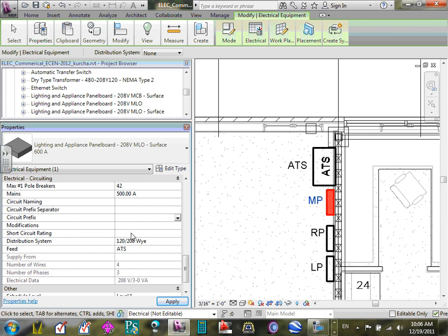Okay, any questions, guys? Later on, Rob, my friend, I will be asking you guys to put the short circuit rating of this panel. We don't know it yet. When we do the analysis, after we find the value, you'll just type there 35,000 amp. That's all. Not now. At any time, you can go back to the project and type this value. As you guys know with Revit, the reason why we populate this is because now you can pull all this information into the schedule. When you run the schedule, everything that you put right now will be on your schedule. Is that cool or what? Am I the only one who's excited here?